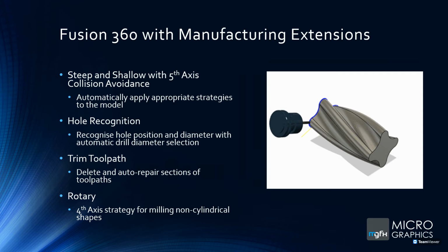Do you want to machine around the fourth axis, as we see in the image on the right-hand side, or do you want to machine along the length of that fourth axis? And this also gives you control over the direction and the limits and also the position of the tip of the tool. So we can see here in the image that fourth axis rotary part being machined.